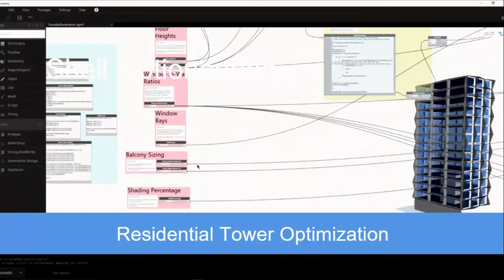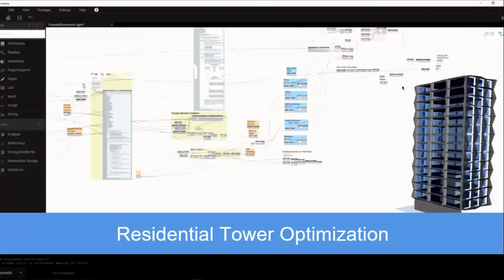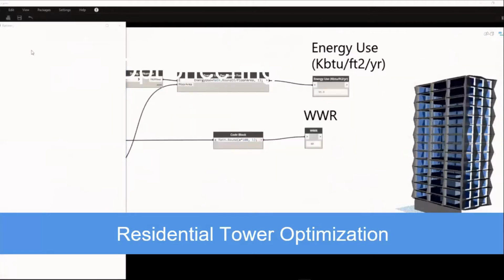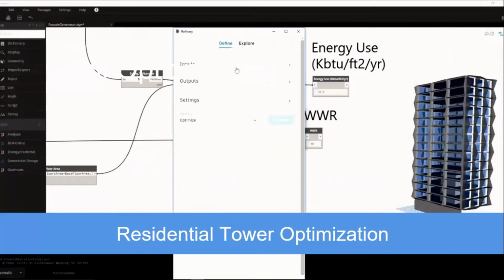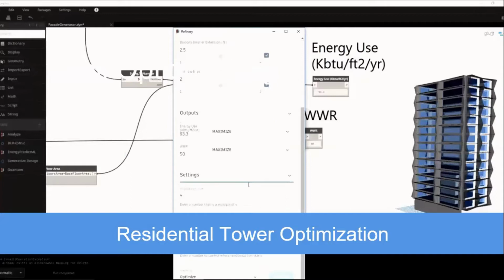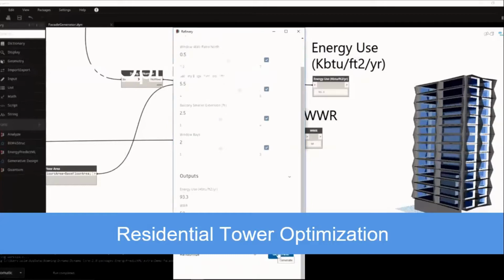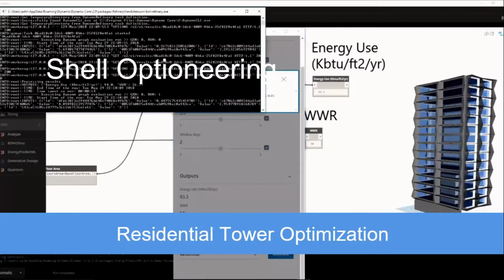You can also control the building shell geometry, the floor plate creation, facade section creation, and facade section tessellation, using the same platform within Revit or Dynamo. Again, if you're using Revit standalone, you'll have to access all these platforms using the generative design plugins that are within Dynamo. We actually call them packages.